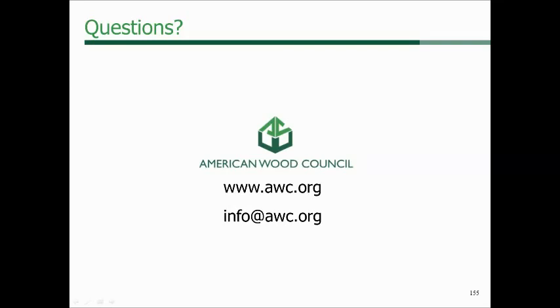However, one needs to think about when you're dealing with the elevator shafts that there are fire resistance requirements, and does that comply with the rated assemblies? So not specific to that material, but there may be requirements to provide that gypsum. Also, assuming that it's in a concealed space, there may be some conditions that require sprinkler protection for exposed combustible materials in a concealed space.